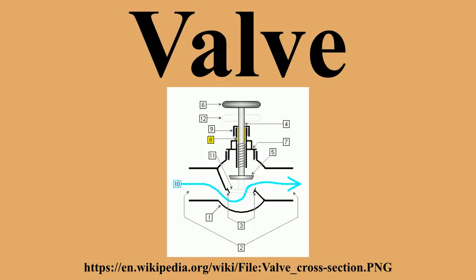Pressure regulators are variations of valves in which flow is controlled to produce a certain downstream pressure, if possible. They are often used to control flow of gas from a gas cylinder. A back pressure regulator is a variation of a valve in which flow is controlled to maintain a certain upstream pressure, if possible.